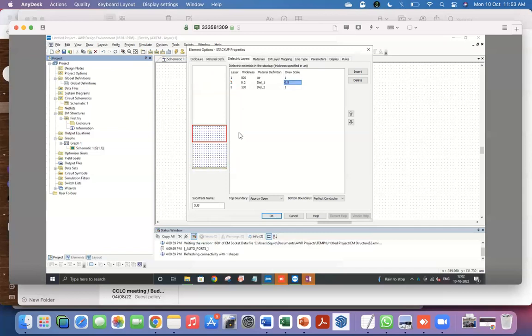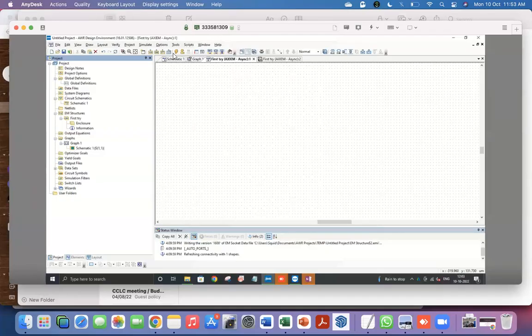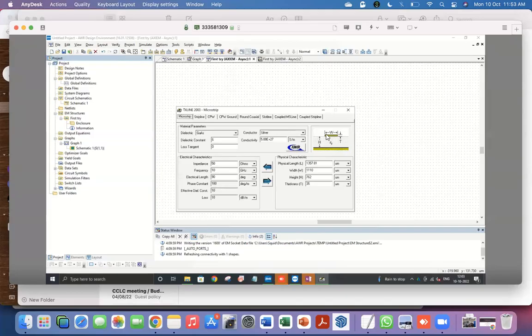Just as I said, if you are interested in a simple, say, microstrip transmission line or a CPW transmission line, essentially the kind of things we were looking at in our lab, this is what we are trying to define now. What is this structure? There's a metallic boundary here, there's a metallic strip here, which is the microstrip line, and then you have your dielectric in the middle.